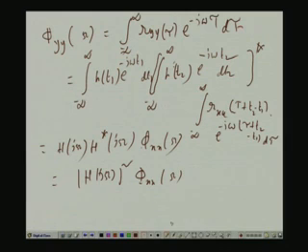Okay. So, you see input power spectral density is multiplied by the mod square, that is the magnitude square, of the frequency response. So, you can design a system where for certain frequencies the magnitude of the transfer function or the frequency response may be high, and in certain other frequencies magnitude may be less, and therefore, at certain frequencies you can boost up the power spectral density, and at certain other frequencies you can suppress. So, you can give a shape to the input power spectral density, which gives rise to the idea of filtering.